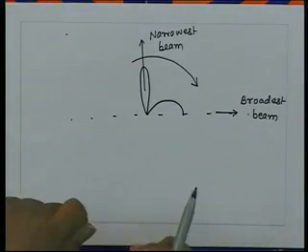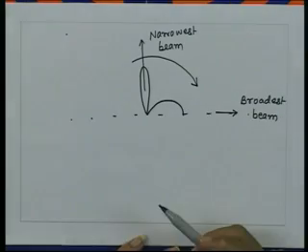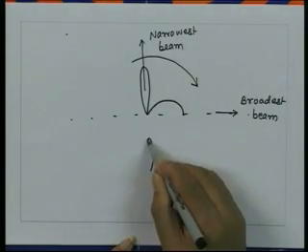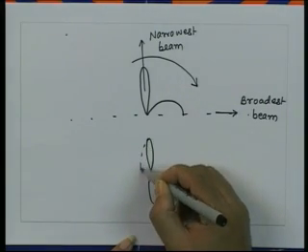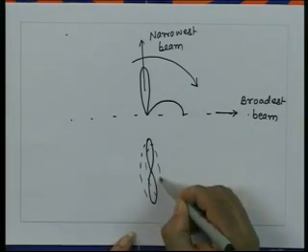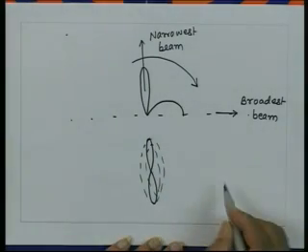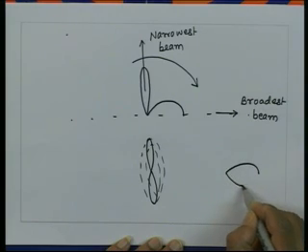However, as we mentioned earlier, you should always look at the radiation pattern in 3 dimensions. If I do that, then the radiation pattern is a figure of revolution around the axis of the array. So, for a broadside array, the pattern would essentially look like that, which is more like a disk, something like this. Whereas when I go to the end fire array, it will be a figure of revolution around the axis, so it will be like that.